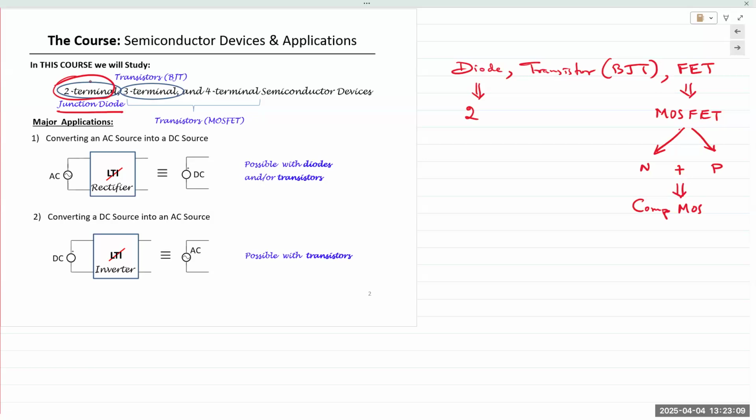Electrons have negative charge. And if you apply a positive potential difference to the anode with respect to the cathode, the electrons are attracted to the cathode, current starts flowing through the tube and the external circuit. Okay, so it's a one-way device. And the name came from the fact that it had two electrodes, diode, two electrodes. When they came up with the semiconductor version of the device, the name carried over, and hence it is still known as a diode. But it doesn't have any actual electrodes in there, just terminals.